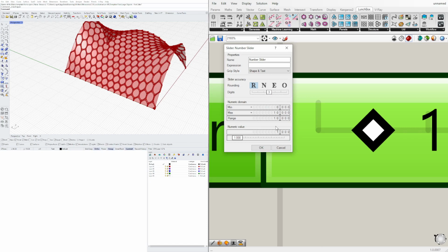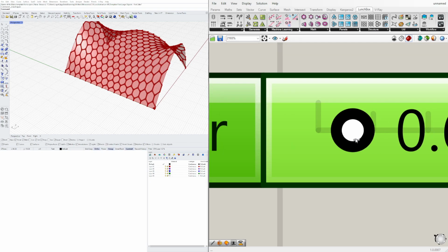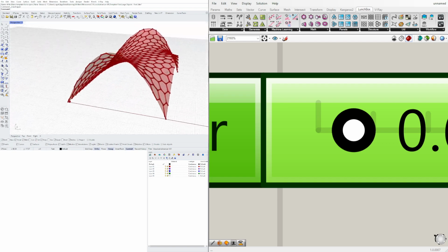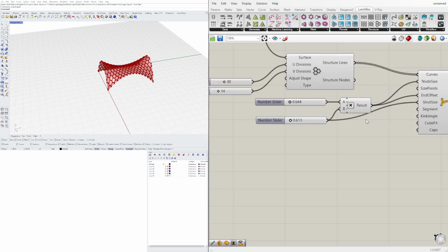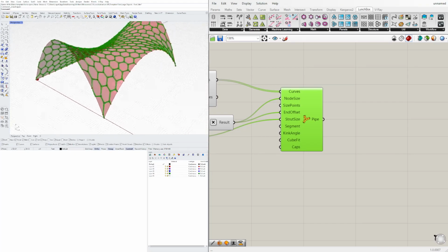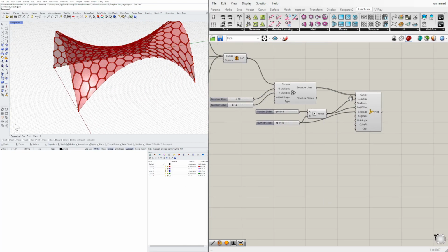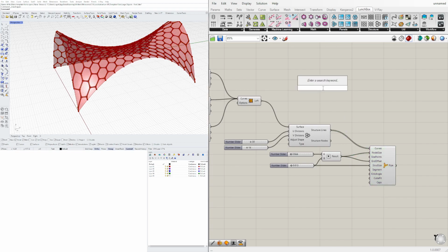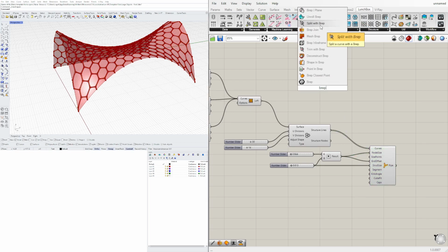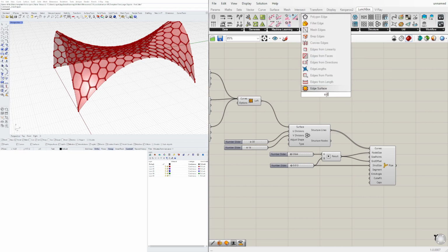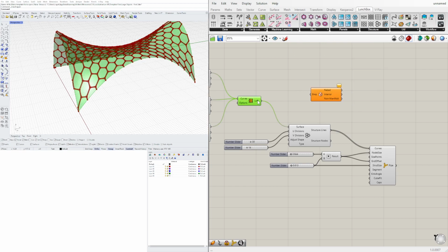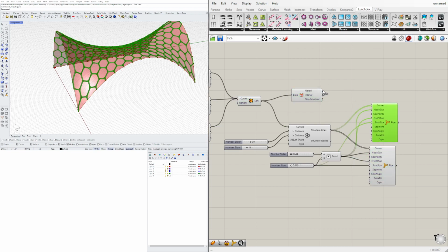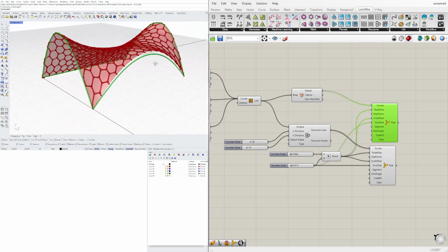Also change this. And as you can see at the end here, we have that design, but we don't have the outside of this. So let's bring in a BRep Edges component and plug in the lofted surface into it. And now we'll copy this and plug in our naked edges, which are going to be the outside ones, and plug those into the curve.